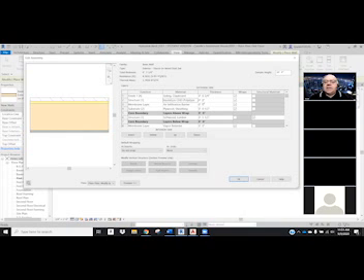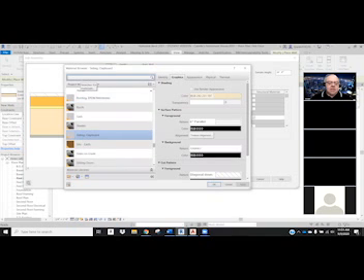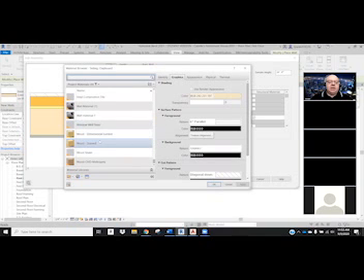So for this, I'm going to go ahead and make it a 2-inch thick stucco on there. So just 2 inches, and let's make this change just a little bit. And then my finish, I'm going to change it from siding. So we've got some insulation at 2 inches, and now we're going to change the siding to paint. And paint's really not the right word for it. It's actually a stucco. Let me see if I put stucco in here for you.